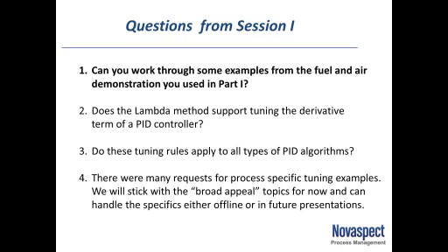The exception is something called the parallel PID. Bailey used to use the parallel. If you're tuning a Bailey controller or some other parallel PID algorithm, email me and I'll show you how to convert the tuning constants from today into something that'll work on your parallel controller.